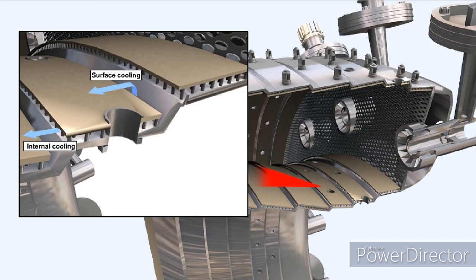Cooling air passes through the holes in the skin and flows between the skin and the tile, which has a ridged surface. The ridged surface improves the heat transfer between the tile and the air. The air finally enters the flame tube at the front and rear of the tile and forms an insulating film for the tile as it flows over it.